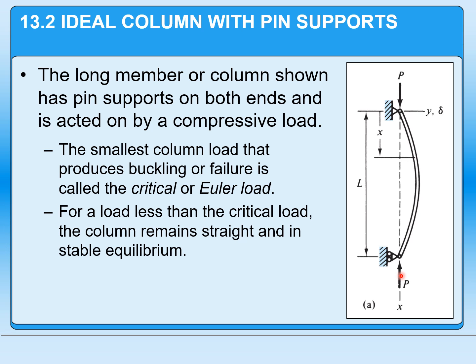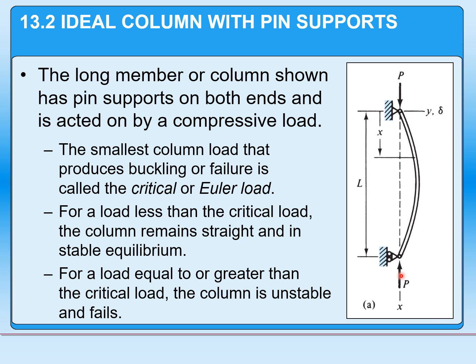Turns out that for any load below that, we really don't have to worry about it. The column acts essentially like a compressive member, and it will remain straight and in stable equilibrium. Certainly it's going to have stresses on it, but the stresses are going to be easily quantified. If it exceeds that amount, that of course is going to cause the column to become unstable, and specifically it's going to cause the column to buckle and fail.